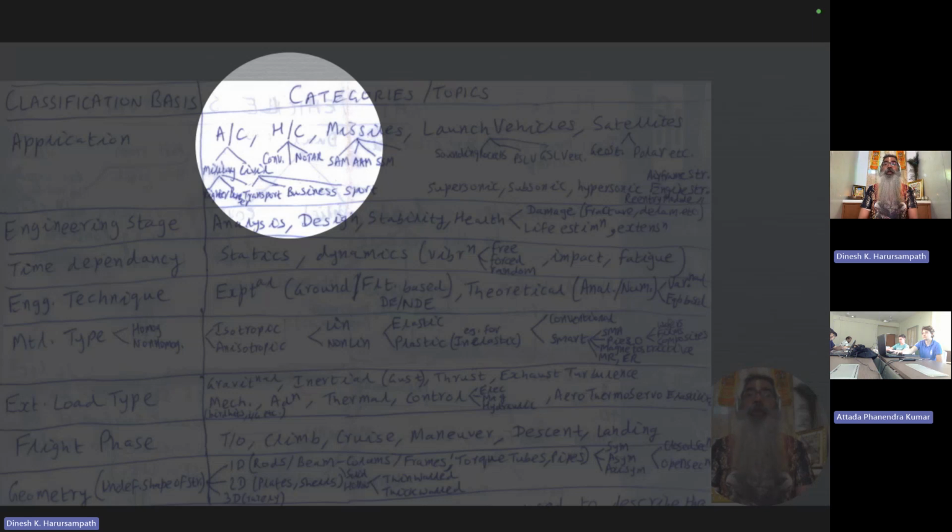When we do the structural analysis for this, we need to take care of some of these complications, which is what we have to be aware of. So in this particular case, there's what is known as an extension twist coupling. In other words, you're extending because of the tail rotor blade, as well as any rotor blade, because of the centrifugal forces that get it pulled, and because it is getting pulled, the pilot is applying the cyclic controls as well as the collective controls through the pitch sticks that he has.